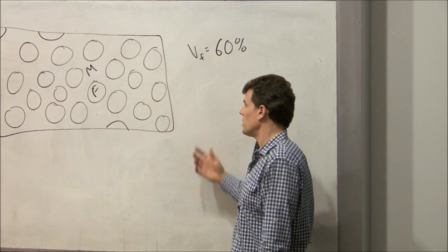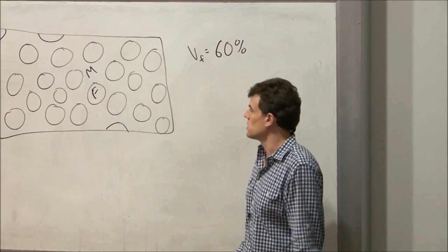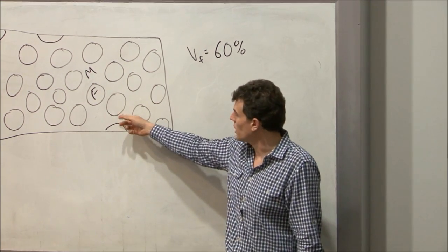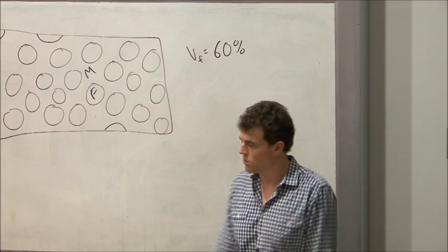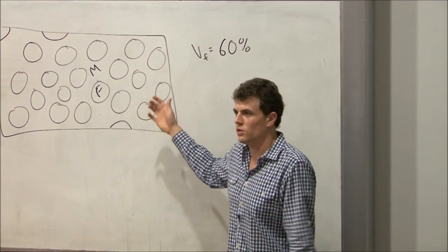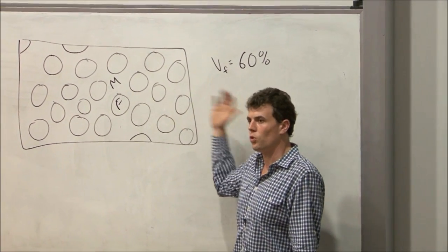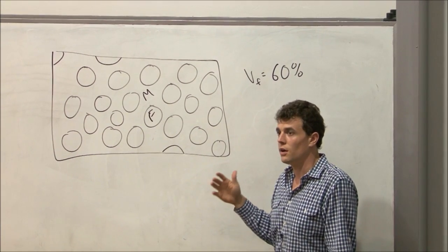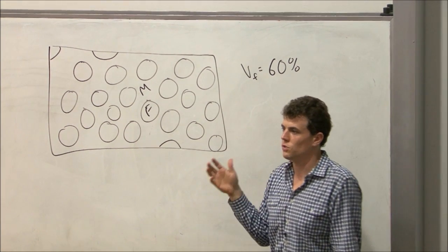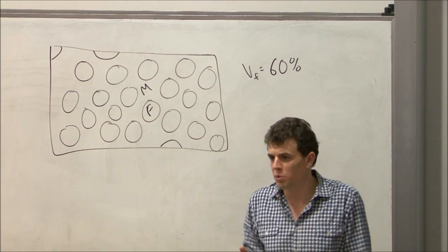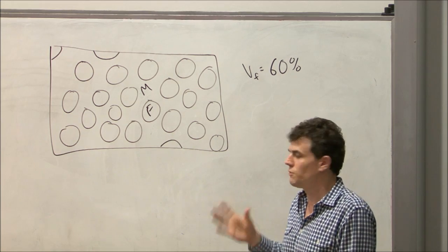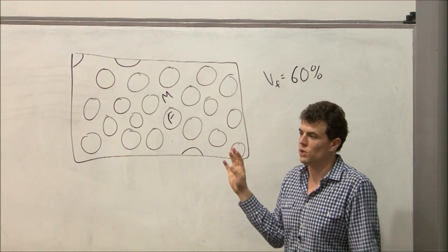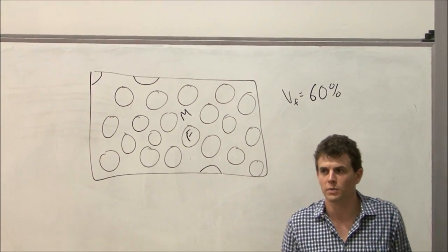matrix. The other way to do it is to do it by weight and using densities, but depending on the type of property you're after, the area fraction is also interesting, because area fraction is the one that determines our properties most, because all of the things we're interested in, like stiffnesses and strengths, are force per unit area. We're used to megapascals and gigapascals. We're talking about a particular force acting on a particular area. So area fraction is the thing that really determines what our mechanical properties are going to be.